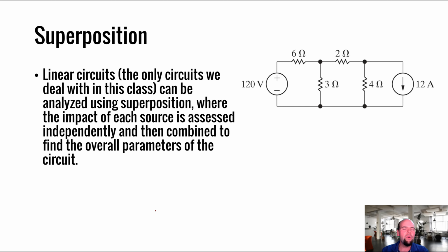You don't want to find the Thevenin and Norton equivalent of a circuit if what you're concerned about is finding all the unknowns in the circuit. But you do care if you want to see what that circuit does to something connected to your terminals AB. Similar thing with superposition. Superposition is typically used when you're just trying to find one or two parameters for a system. You're not trying to solve for all the unknowns. If you are, just use node voltage or mesh current. When you want to find a limited number of things, it can be a useful tool.